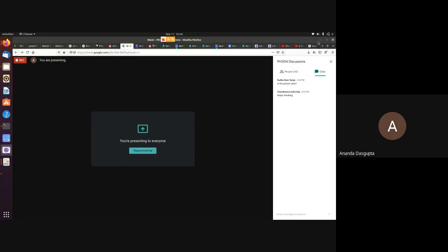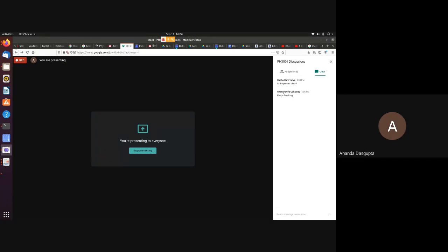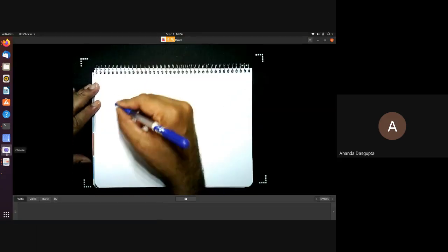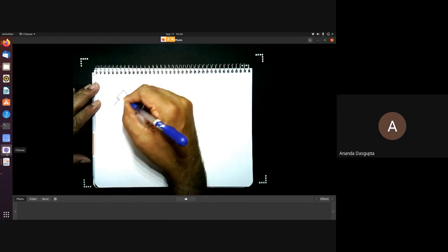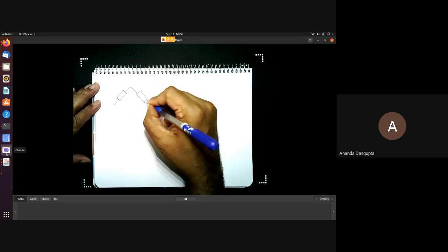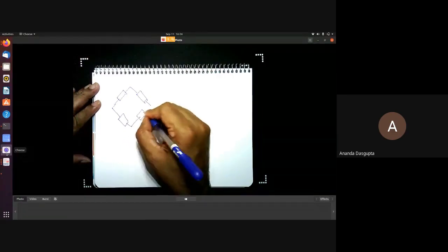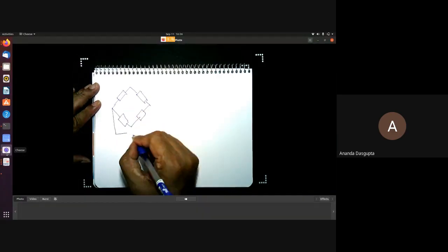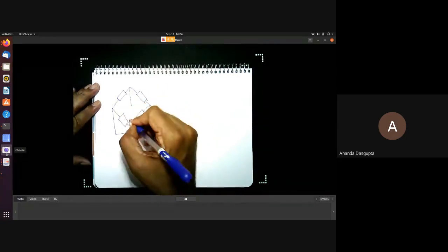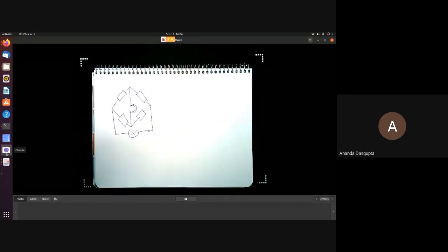Okay, so now let me quickly ask you this. We talked about the AC bridges in the last part of lecture 7, right? And the idea essentially was it's very much like a Wheatstone bridge, except that you put in an AC input and from the output you use some kind of AC detector which we did not draw in the circuit there, maybe could be just a pair of headphones.